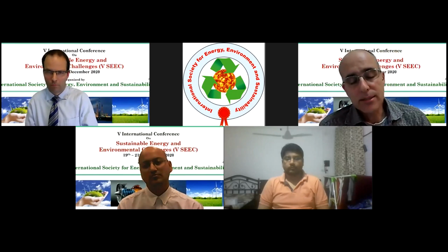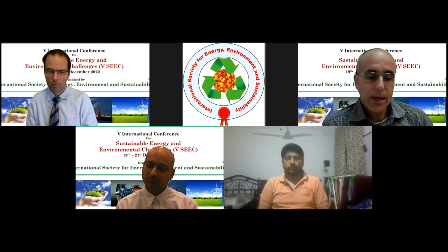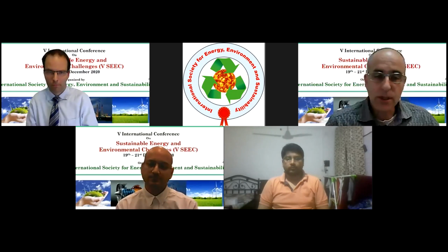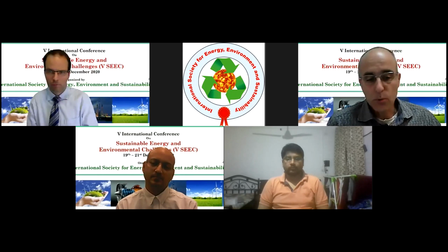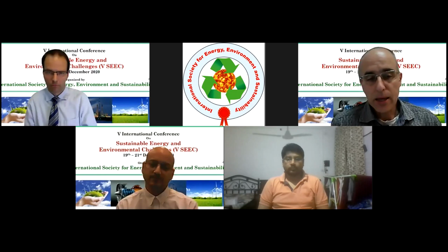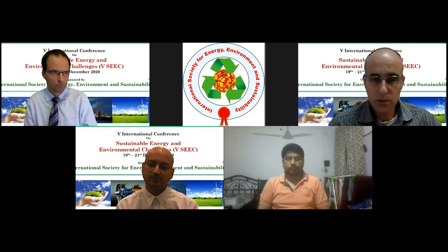So these types of minerals, of course, depend on the source water. And in brackish water, we have large variations of the water chemistries, which depend on the water source, the geography, and the types of aquifers. I think that other strategies will be needed, for example, membrane modifications that will be specific to a certain source type of water.